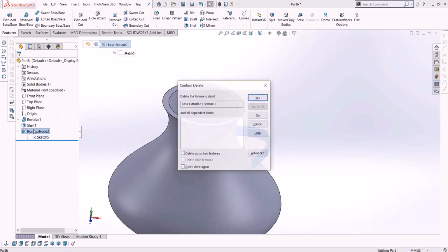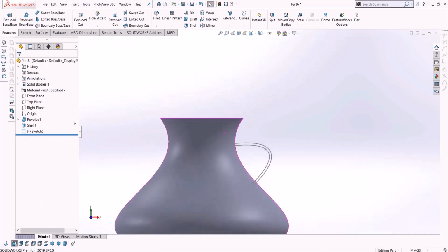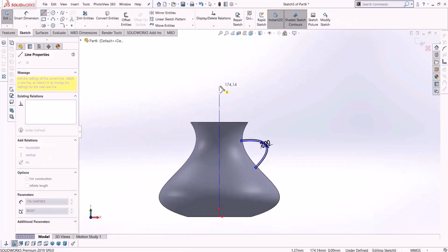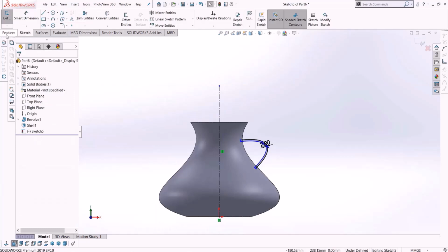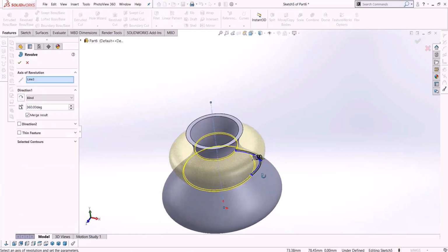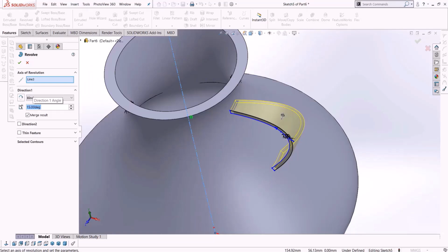If your design is really like this, you can use it. But we said there are right and wrong methods. Now let's test another method together. Even this shape, we still took it into the meat. Let's draw a line here using the revolve tool. Well, this shouldn't be a hasty decision. Instead of 360 degrees, I set it to, for example, 15 degrees.